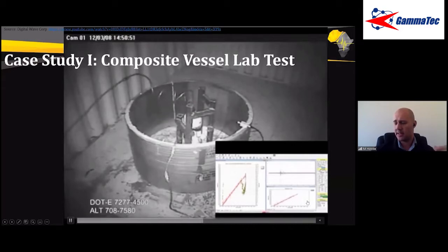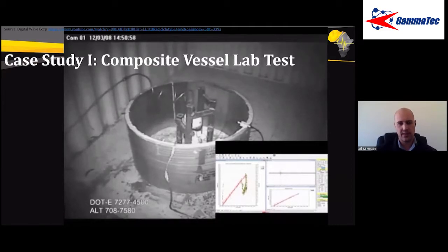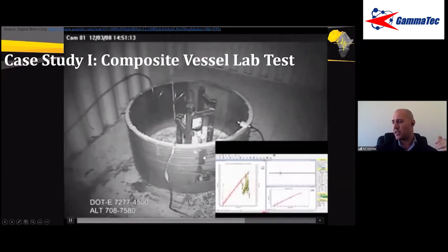There's some acoustic emission, and at this point, as soon as we see this oscillation, the acoustic emission technician or field engineer on site would immediately tell the pressurization team, well, hang on, you need to slow down, stop, let's investigate further. And about at this time, we would be screaming on the radios to tell the gents to stop pressurization as we just gap it basically away. You can see there's no visual cues on the vessel yet, but the acoustic emission is, you can definitely tell that, hang on, something is going on there. There's some cracking, there's permanent damage happening to the structure.